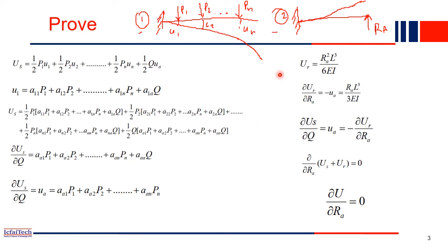Now we have to find out how much deflection happened here at the end A. How will you do it? We can simply employ, because these are two determinate beams. The original beam was indeterminate, and we made it into determinate beams. So now we can employ Castigliano's theorem or any geometric method we discussed earlier, and we can find the deflection here or here, at any place. So let's employ Castigliano's theorem to find how much deflection happened at this end.